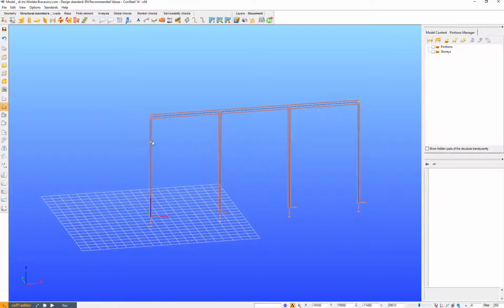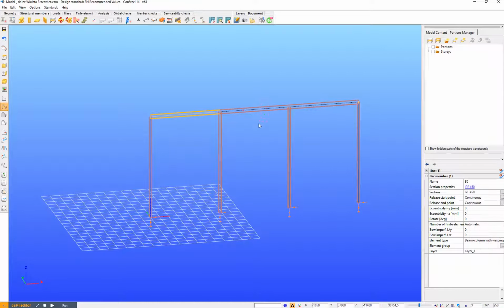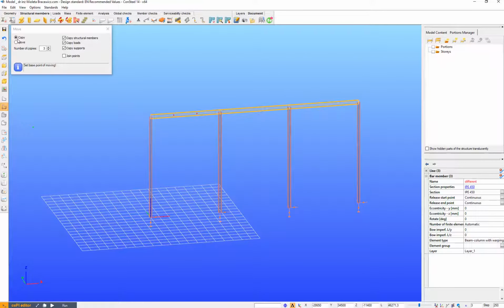Now I have the dividing points, which divide our bars into 4 segments, but I can change it to divide into 3 segments. Now I will copy it, and every story is copied just like that. Very easy and fast.